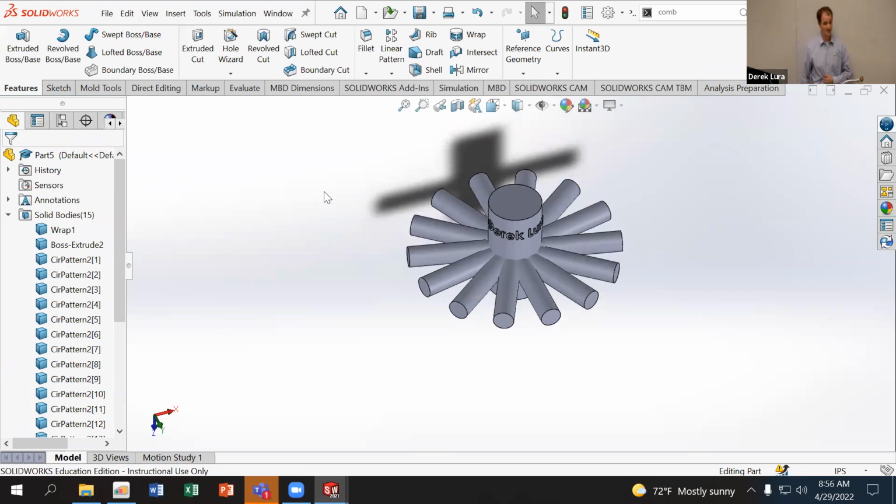So if you're trying to use a mirror or a pattern and it's not letting you do what you want to do, change your geometry to make the thing you're trying to mirror, either the whole part or just a subset of that, a separate body, do the pattern or the mirror with that body, and then merge them back together after the fact. And then that allows you to get to, again, more complex geometry faster.